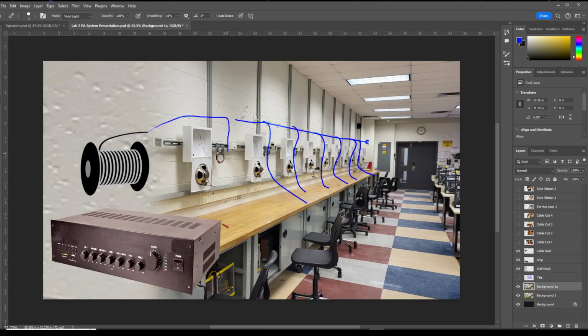Now, pull this wire, and don't try to save a couple of inches of the wire. Run it about here. And that's how you're going to do that. And over here, you're just going to tie it off with the zip tie. We're going to do that starting from the furthest speaker, and then this one, and then that one, and then that one. This way, we just keep unrolling the wire from the reel.